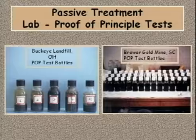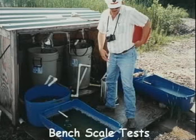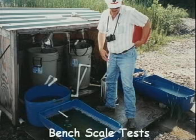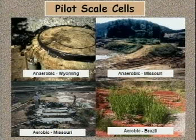The bench scale test is the next phase. This can be a field test, or it can be conducted in a lab if it's easier to bring the ARD there. Bench tests typically take 3 months or more. Now it's a dynamic test with flowing water. We typically use 5 or 6 cells to evaluate various mixes of substrate components and include different cell types and sequence as shown in this slide. The construction materials, as you can see, are pretty simple. In this case, we use off-the-shelf trash cans and plastic barrels cut in half. And the bench results provide the basis of the pilot test design.